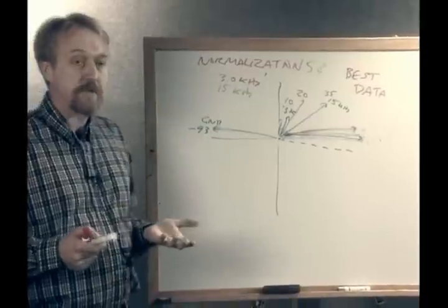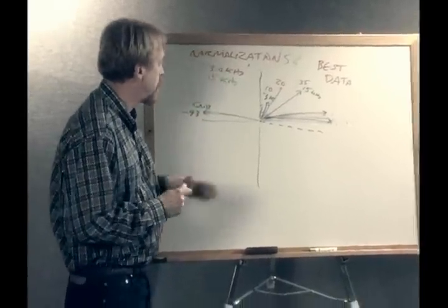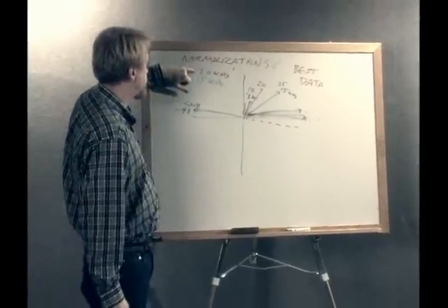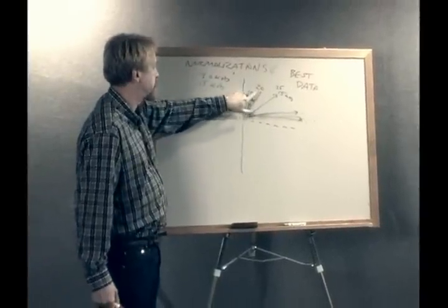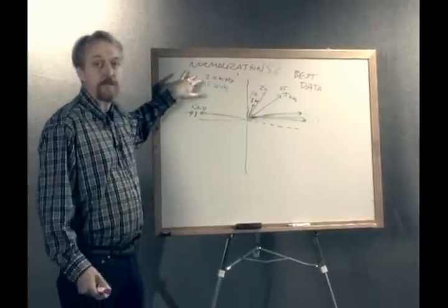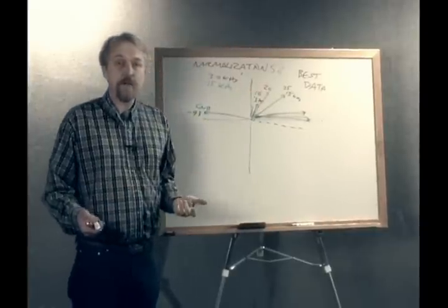But that brings me to the next two-frequency mode of operation, which we call correlation. If I pass over the target and the determination at 3 kilohertz gives me a result of 20 after I've done the normalization, and at 15 kilohertz it also gives me a result of 20, then I've got a pretty high degree of confidence that that reading is correct.